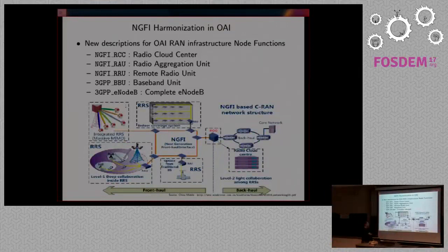You have what's called a remote radio system where there's a lot of collaboration between the nodes. So you have big base stations, tri-sector base stations with 6 or 12 antennas, and then you have smaller picocells. But the signals are all collected at this radio node here. This is different from today's networks. These radio sites will have a fiber optic connection from the radio head down to a control room at the bottom, which is basically where all the baseband processing is happening.